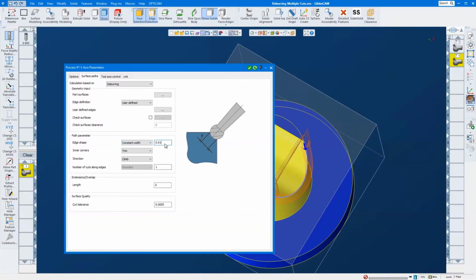We've defined the width. Then what I would imagine is, depending on how it can tilt the tool, but let's say it can't tilt the tool, so say it is a 3-axis part, then there's only going to be one chord on that ball that will give you that width and remove the same amount of material from both surfaces.